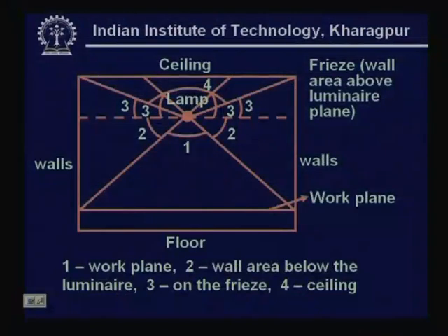So there it was necessary to suspend the lamps, whereas in modern buildings the ceiling heights are lower these days. Especially for interior work where a controlled environment is necessary, keeping in mind the load it may pose on the air conditioning plant, they are always provided with false ceiling and the lamps are placed recessed in the ceiling.